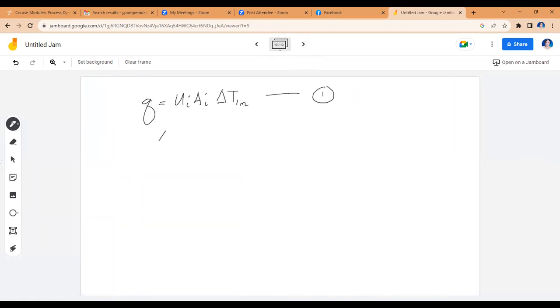And we'll have the delta T log mean. So the delta T log mean is delta T2 minus delta T1 divided by ln of delta T2 over delta T1. Okay? Now, there's a question. Can we interchange these two, Miss Ali? The answer is yes. If you make this delta T1 and delta T2, make this also delta T1 and delta T2. Whatever is the order you're subtracting here, that's the order in which you're going to divide them in the ln expression in the denominator.